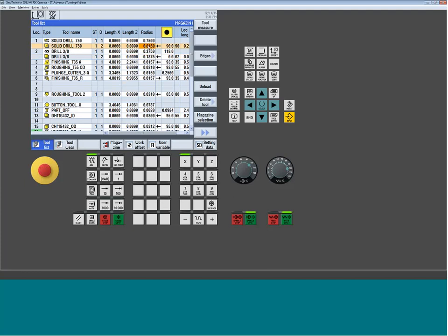So the nose radius of the tool. What is the relief angle? This is a straight one. So I want to use 90 degrees with a 90-degree insert. What is the IC diameter? Usually these drills have some pretty small inserts, so I was using a 1/4 of an inch IC. And that builds the tool.